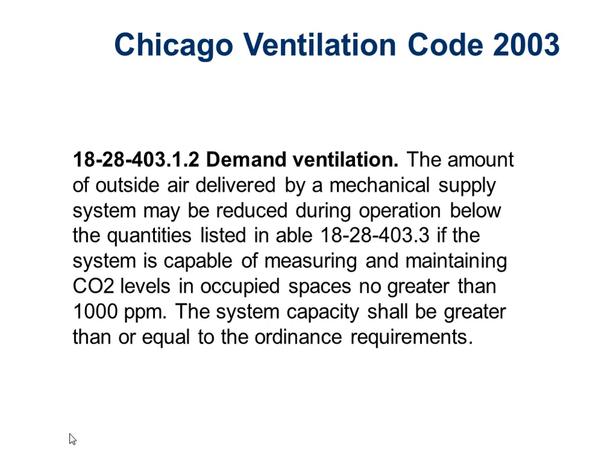If you recall, I said with the ASHRAE and IMC, we're basically looking for a difference between inside and outside. For an office building, it's basically 700 parts per million difference between inside and outside. For the city of Chicago, it's a little bit different. They give us a fixed parts per million set point for the indoor occupied space of 1,000 parts per million.